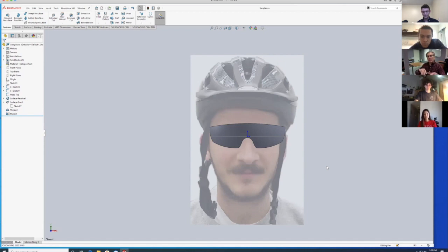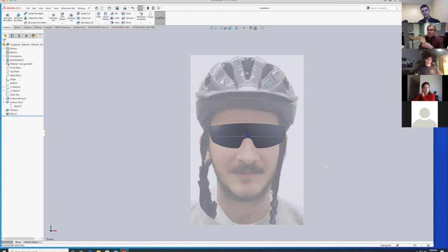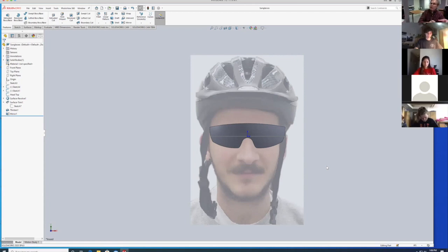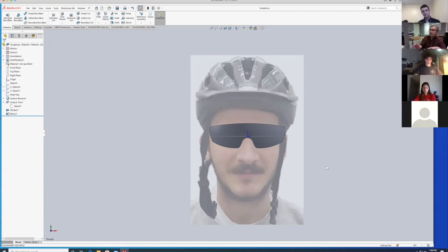There isn't solid. So with Rhino, if you drill a hole in something, then you have to add the inside surface of the hole. I believe, unless they changed it, that's the way it was. With SolidWorks, you drill a hole in a block, and it's as if you just drilled a hole. There's a bottom and cylindrical sides on the hole you just drilled. The other thing that's different is that it's parametrically driven. So rather than the geometry driving what the dimensions are, in rough terms, the dimensions drive the geometry.